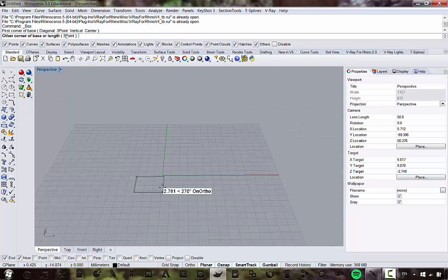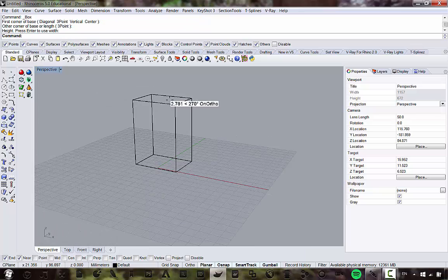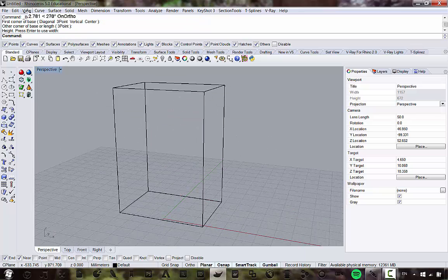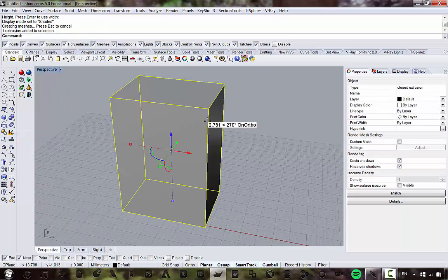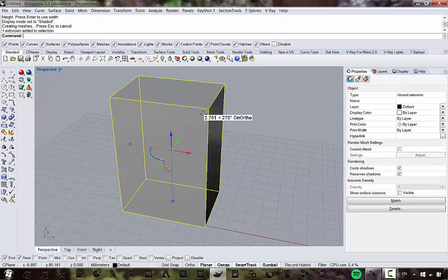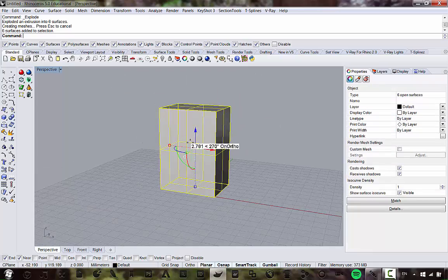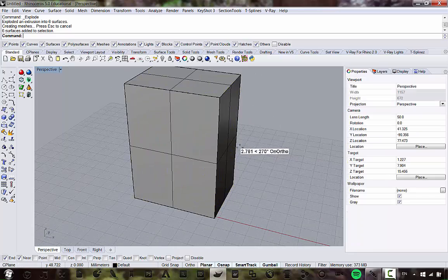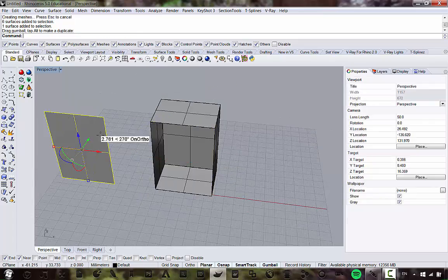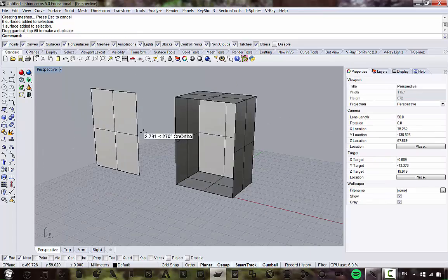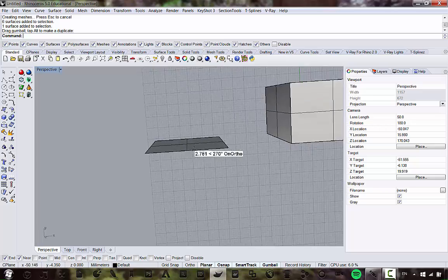But anyways, what we're going to do first is the difference between surfaces and solids. So just to review this. This here is a solid. It's an extrusion. I'm going to go to shaded. If you're wanting to 3D print, you want to see closed. If you explode this, you're going to get 6 open surfaces. In this case, you can see that it's flat. These are infinitely thin.